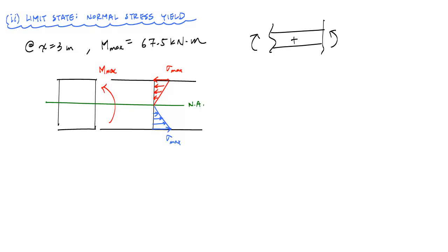Also, we know that the bending formula, or the normal stress due to bending, sigma is equal to minus My over I, where I is the moment of inertia of the cross section. And this y is defined as the distance from the neutral axis upwards. We're going to utilize this formula for our basic design relationship. And really, you can tell already the moment of inertia is that one parameter, in addition to this distance y, that has the geometry of the cross section in there. And so here's this b and here is this h that we're really trying to figure out.